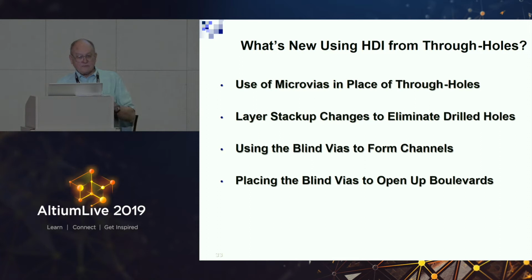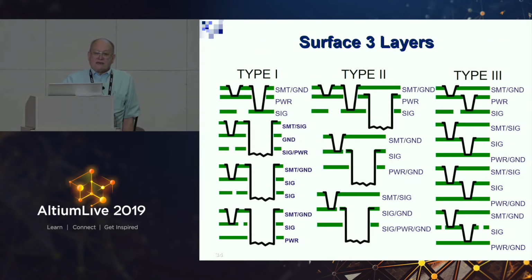And so, depending if you have type 1, type 2, or type 3, figure out how to bring that ground plane from layer 2 up to layer 1. Now, not only does that eliminate a via, but it eliminates the EMI problems of radiation. Because now you have the opportunity to create a Faraday cage to trap it.